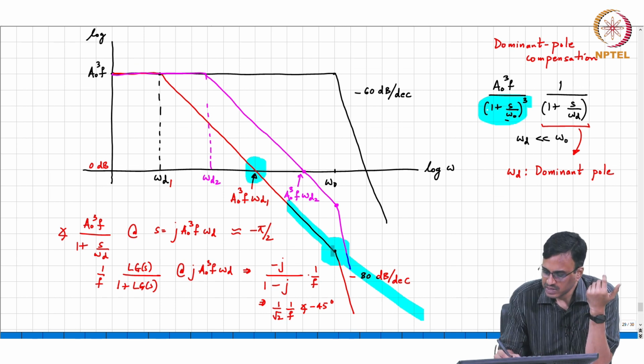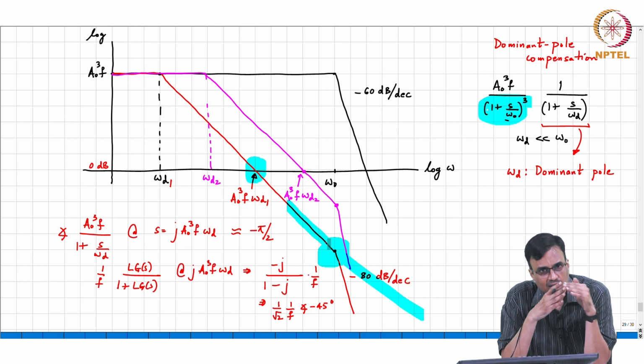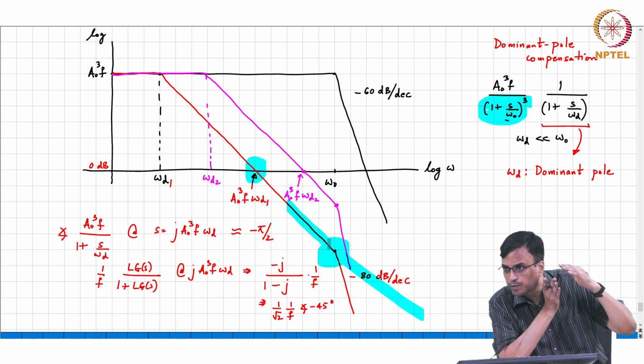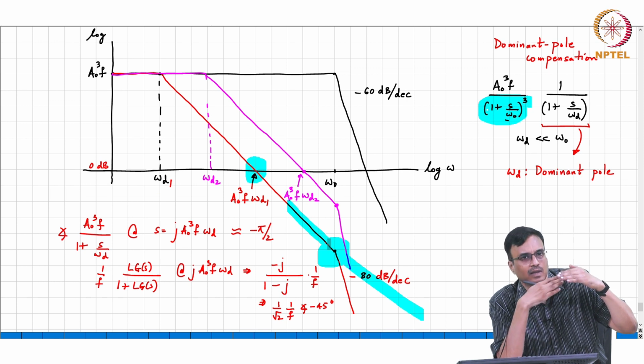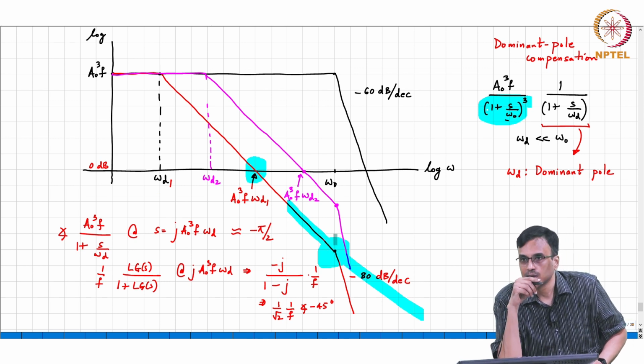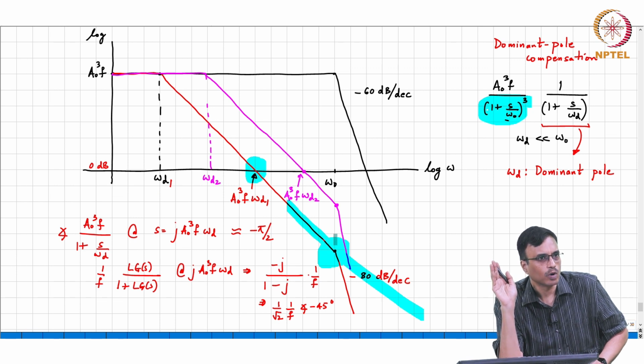Basically what you are saying is you will measure the magnitude of the loop gain function at which the Bode plot of the higher order system deviates from the actual true first order system, correct. And if the magnitude is smaller, it is a better approximation to a true first order system. Does it make sense? Is that clear?